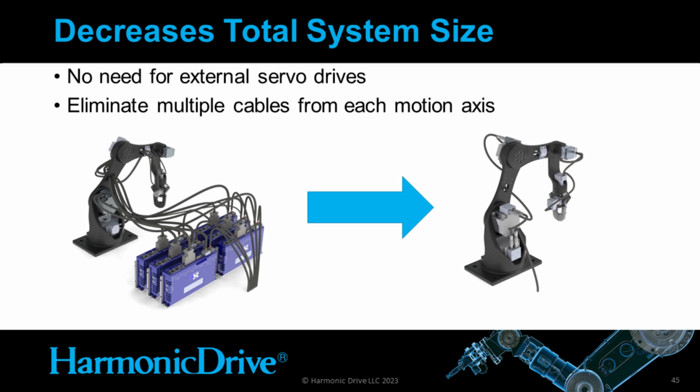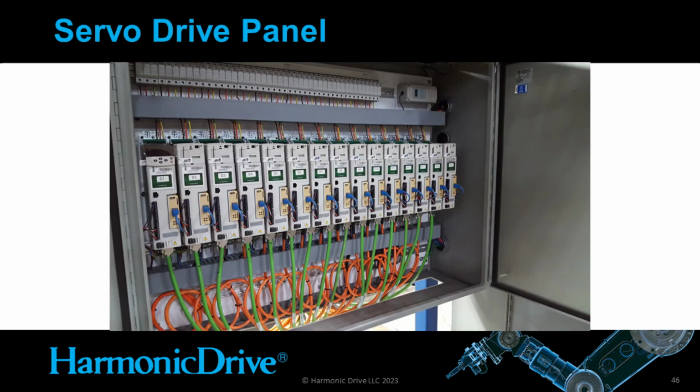So thanks to their servo drives being under the cover and thanks to their minimal increase in size, there's no need for external servo drives, and this eliminates multiple cables from each motion axis. So this saves you all of this room in your application and allows you to have this free space freed up for something else.